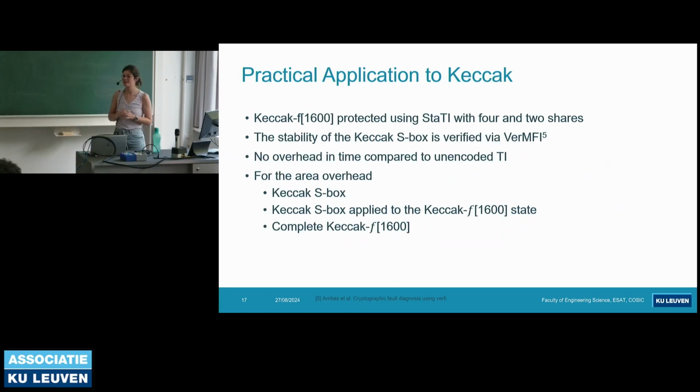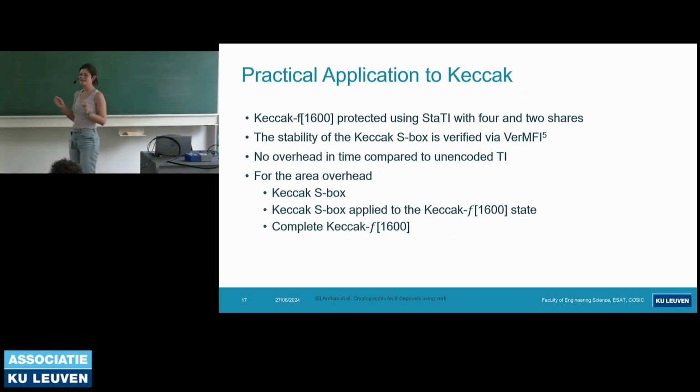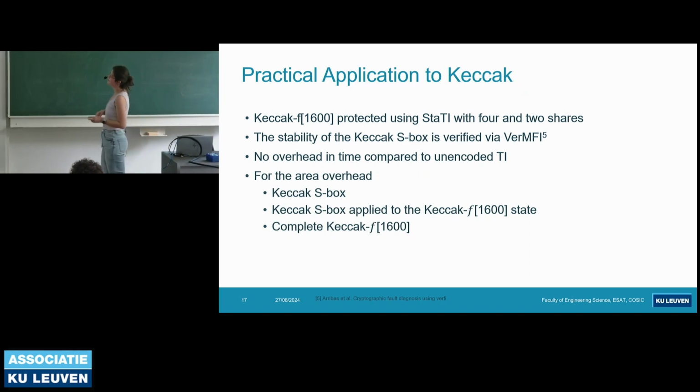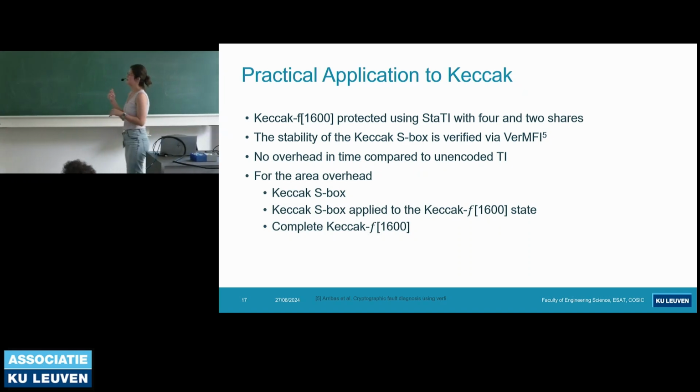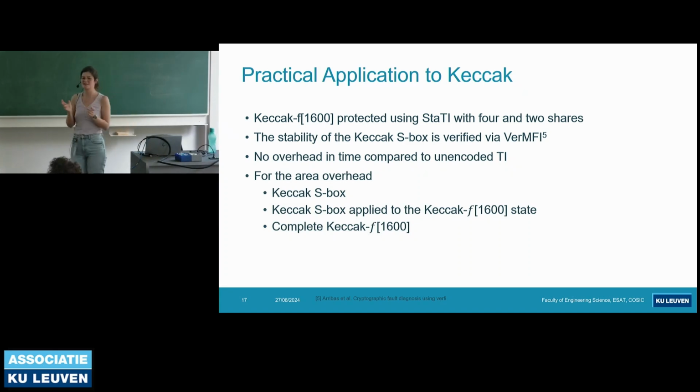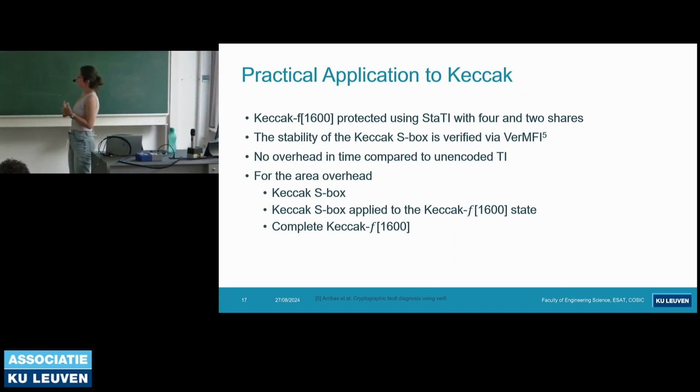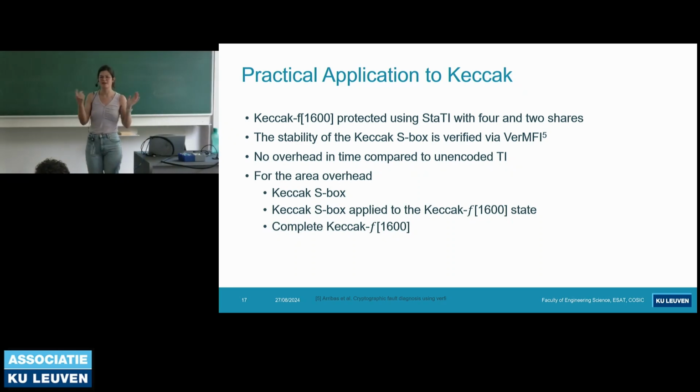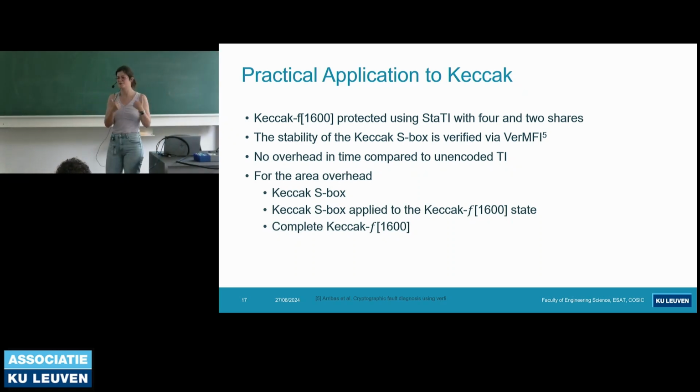Now this was the theoretical part of the paper. And then in the practical part, we implemented StaTI to protect Keccak. In this work, we implement Keccak with 1600 bits, and with 4 and 2 shares. And then we check the stability of the implementation, and we verified it using the MFI tool, an open source tool for fault verification. What we can easily see is there's no overhead in time when we compare those implementations to unencoded TI, and this is the first good thing.